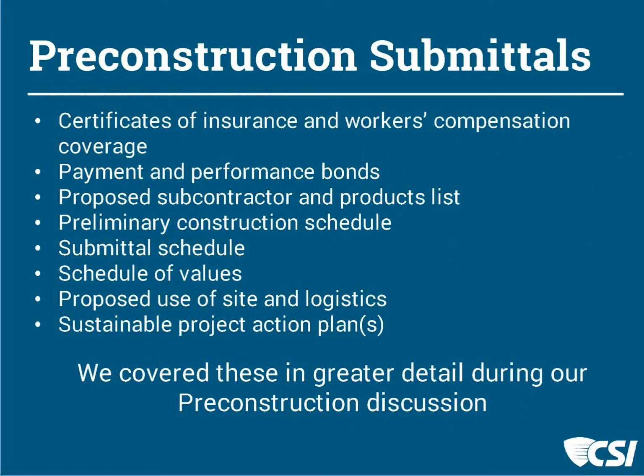The submittal schedule we just talked about a little bit. There may be a logistics submittal for how the site is going to be used, particularly if it's in connection with an existing facility, if the owner is going to remain in operation. And sustainable project action plans with projects that might, in the end, receive some sort of a certification. Maybe just a few examples of what may be considered pre-construction submittals that you would look at and take action on.